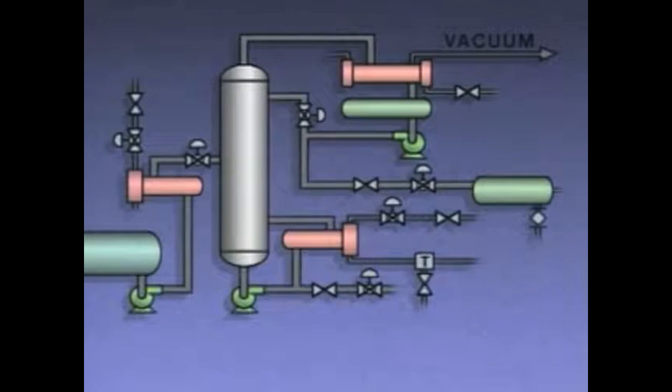At this point in the procedure, there's a continuous flow of product out of the column, and there's a continuous flow of feed into the column. However, the rates of flow may be below the design values for the system. By gradually increasing the feed rate, the product takeoff rates will automatically increase as well, and the startup procedure will be complete.